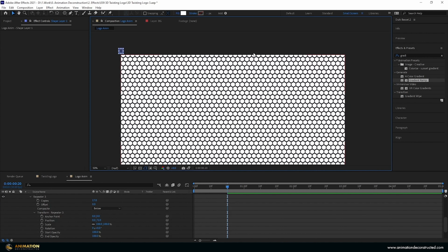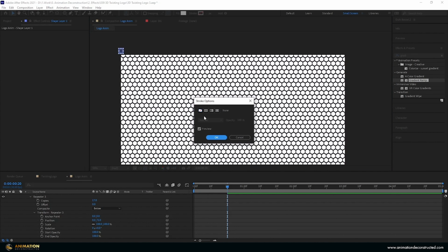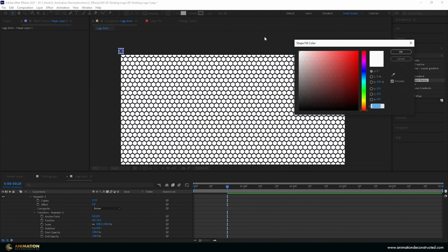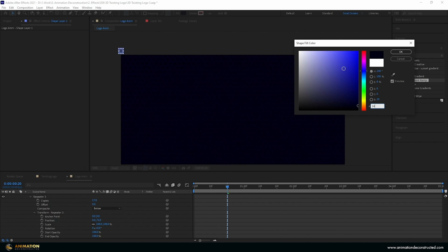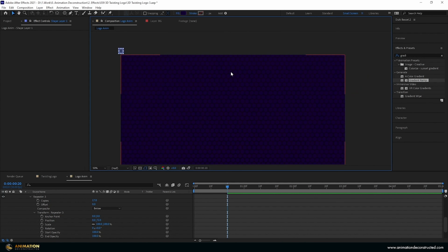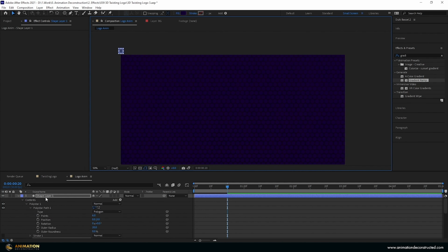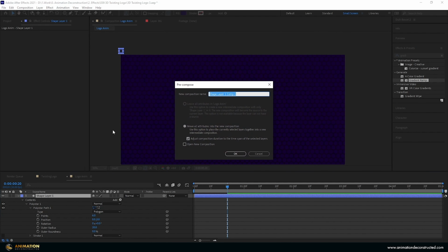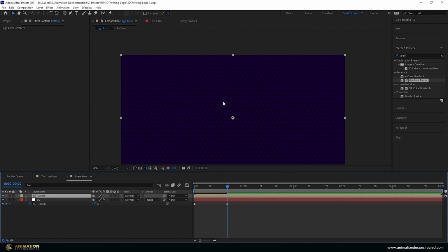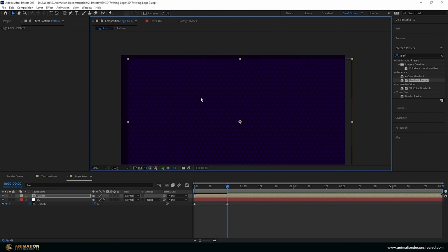Last thing I want to do is change the color of this. So if you've got a stroke on yours, just come over to stroke, turn that off, come over to the fill, make sure you've got a solid fill, and we're going to change the color of this to 140033. I'm going to press OK, and then I want to pre-compose this. So selecting the layer, Control Shift C to pre-compose, and we will call this pattern. And we're going to move all attributes into the new composition, press OK, and we have our polygon texture.